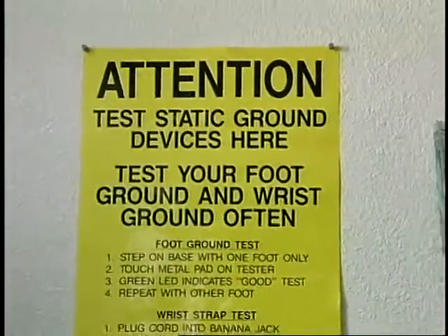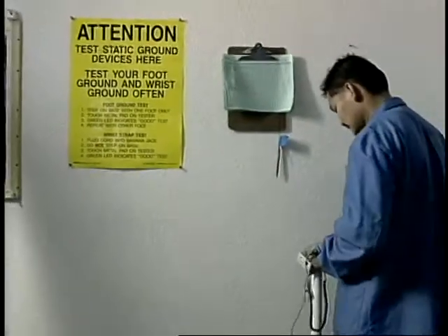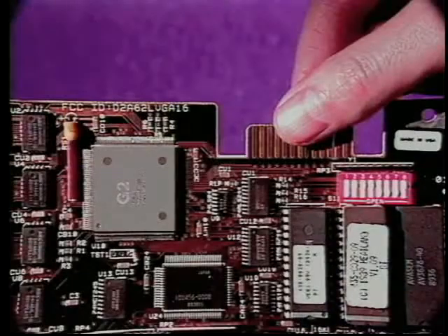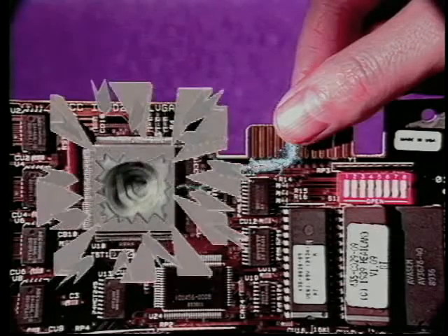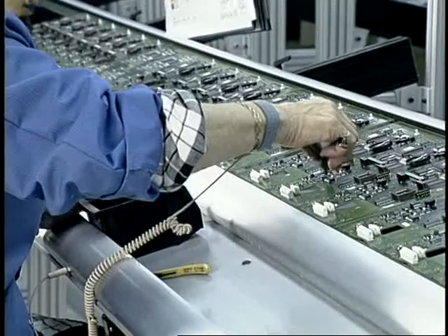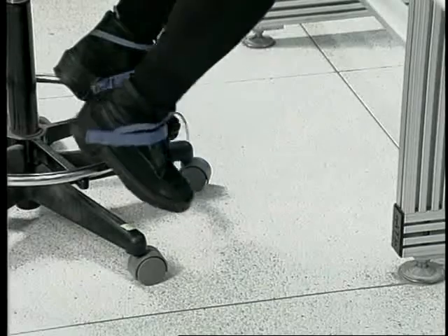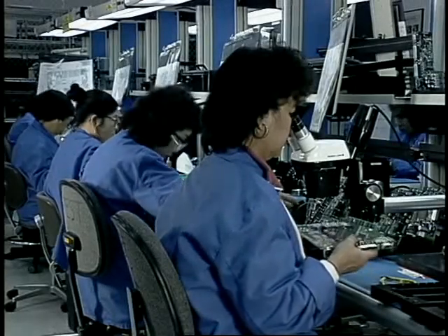Another critical handling issue in electronic assembly is electrostatic discharge, or ESD. ESD occurs when static electricity from your body comes in contact with and is discharged into an electronic component. This electricity can degrade or destroy the functionality of some types of components. To prevent ESD, you must always wear wrist and/or heel straps when working on electronic assemblies. Also, grounded workstations and static dissipative mats and work surfaces will help to protect the assemblies.